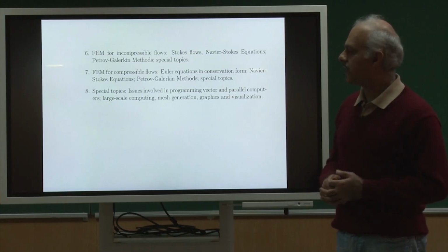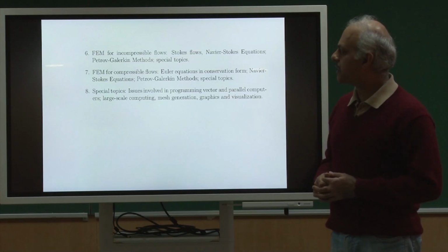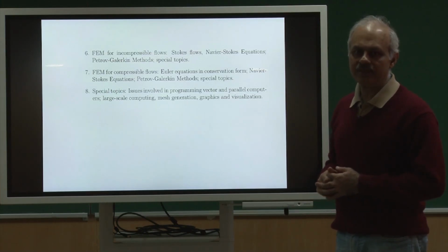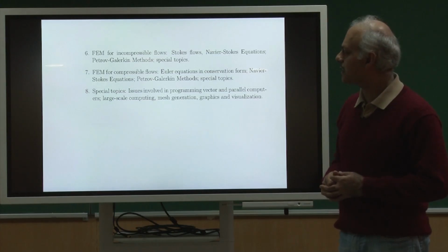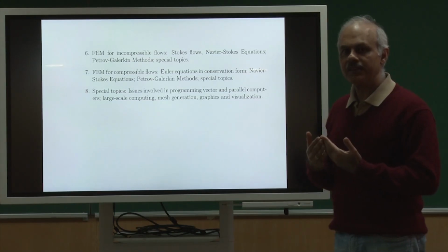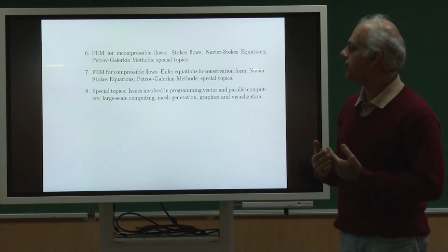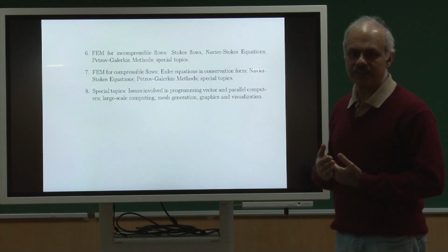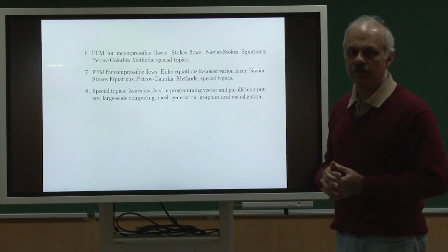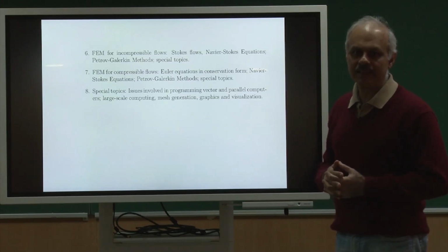As you are aware, in the incompressible flows, the pressure term is one order lower than the viscous term, which actually is driven by the velocity. So this kind of incompatibility between the order of the various transport terms in the equations also has implications on what is the order of representation that I can use numerically.